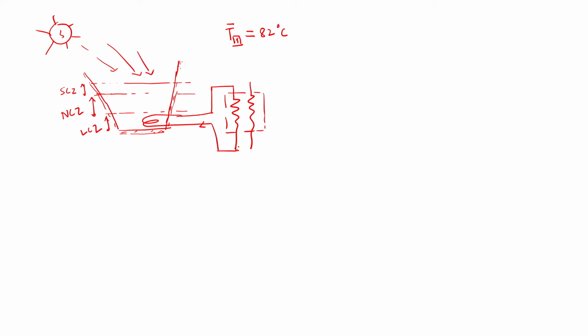And this is connected to here, and here we want 82 degrees C. So already this is given, and we will have this Rankine cycle. In the Rankine cycle, what happens? We will need some kind of working fluid. Since this is a low temperature operation, we need some kind of refrigerant or organic fluid.